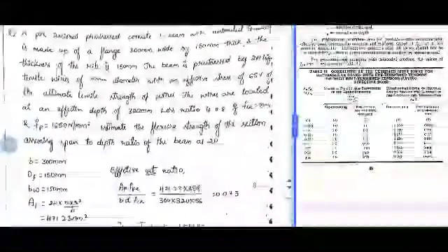So here it is given as post tension unbonded tendons, that means it is unbonded case, and here in question it is given T beam, it means flanged section. So unbonded flanged section, it is case number 4. The flange width it is 300 mm, flange thickness 150, web thickness 150.